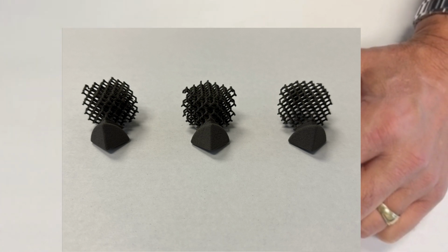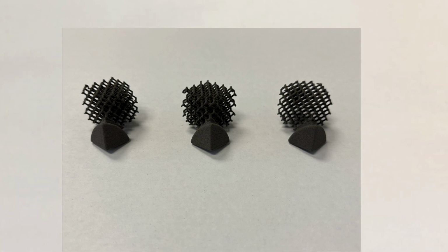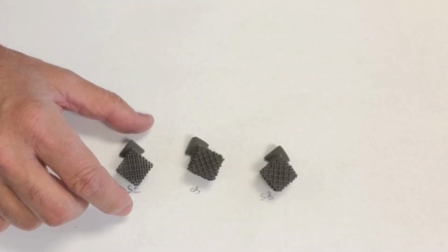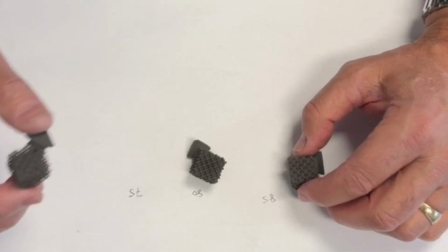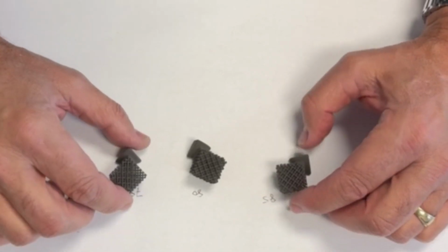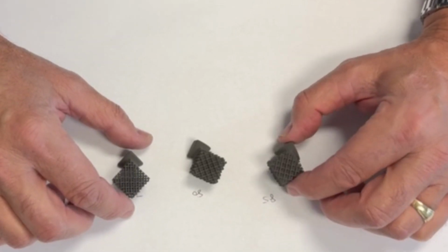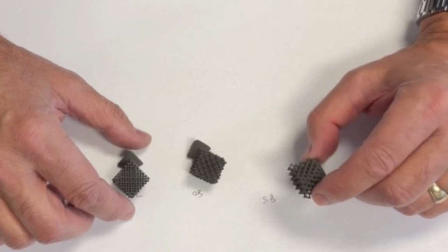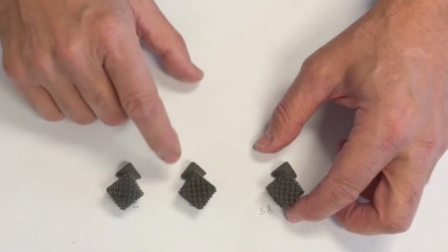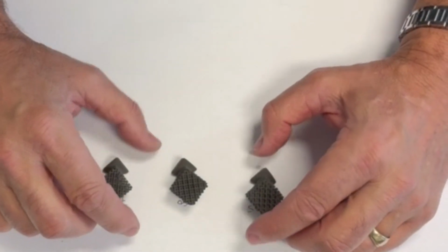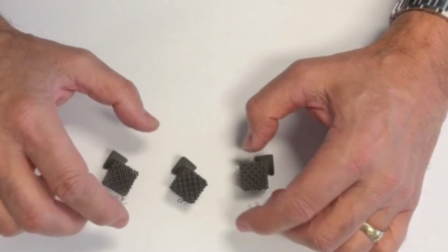In fact, when I look at this, and I can show you here, location on the print bed probably has an impact on some of the results. But the overall densities of these parts: this one was around 0.96, and these were a little bit higher. Actually, the 85 was 0.96, and this one was the heaviest, and this was printed in the middle of the bed. So this was a good way to see thin walls, and I didn't see any impact.